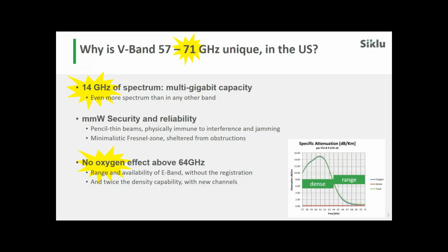There are other standard PoE PSE devices available on the market. Not all of them can go all the way to 95 watts. And that is why at Ciclo we have decided to provide at least a few options of our own. But you just have to pay attention to the amount of power that can be delivered by the source and confirm that it's going to match the amount of power that you want to get out of the PoE.